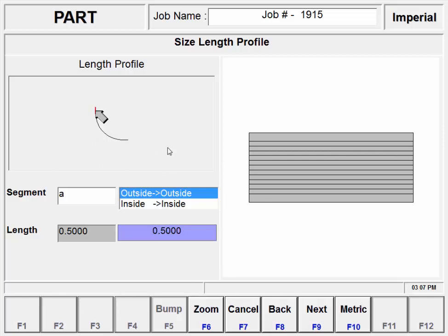So if I use my right arrow, I can step through the different bends, and you can see what it did essentially is it created a bunch of segments. A line, in this case, it's a length that's 2.285 long, and then another bend point, and it's bending it at 171 degrees. Another 0.285, 171. So it does that along this line and creates this radius. Does a pretty good job of calculating this.